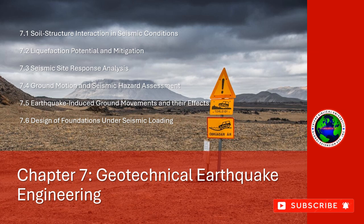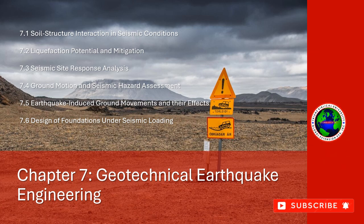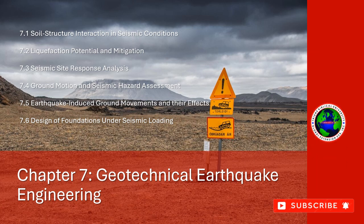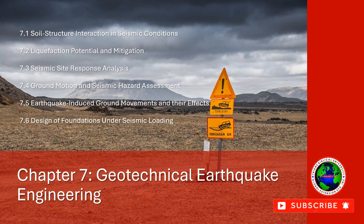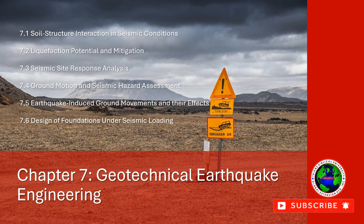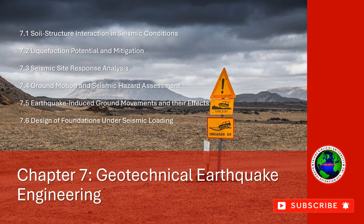3. Dynamic analysis and response spectra. Dynamic analysis is used to evaluate the foundation's response to seismic loading. This involves using response spectra to calculate the peak seismic forces on the foundation based on the dynamic properties of the soil and structure. The analysis considers both horizontal and vertical components of seismic loading.